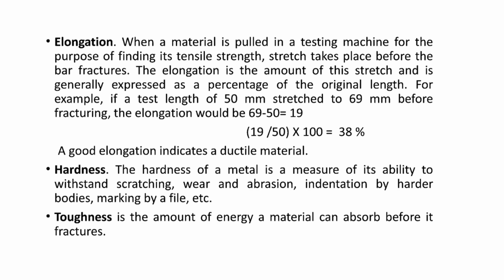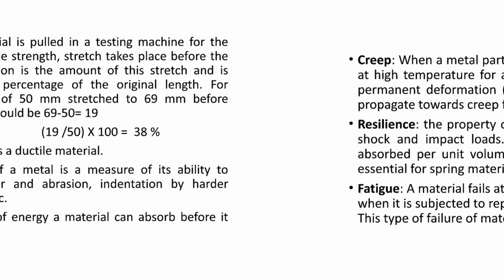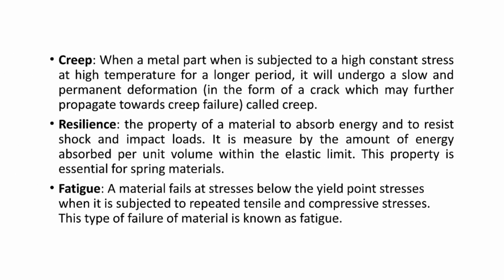And finally, let's wrap up with 3 more critical concepts, especially when considering high-temperature applications. Creep. This occurs when a metal part is subjected to a high constant stress at a high temperature for a longer period. It will undergo a slow and permanent deformation, often in the form of a crack, that may grow and lead to what we call creep failure.